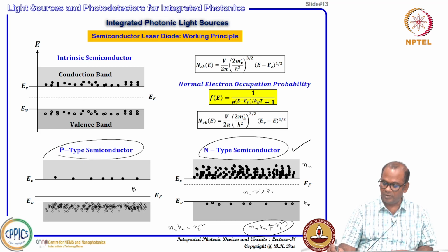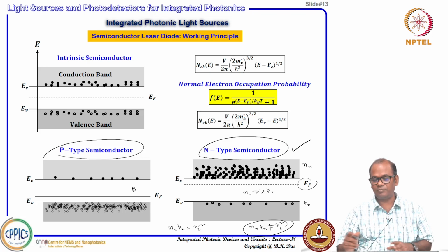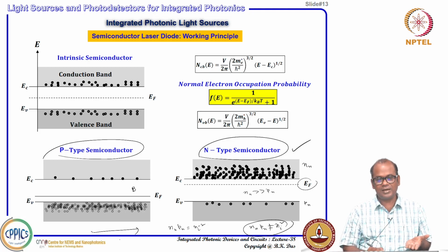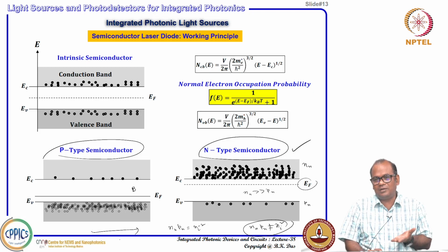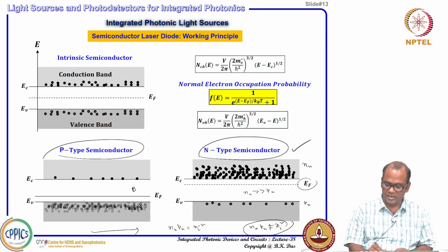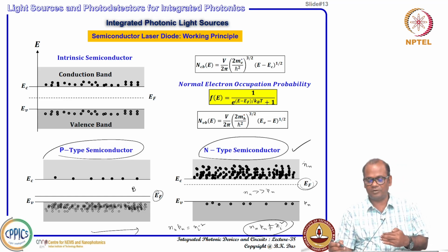where a pentavalent material is doped, so that a lot of electrons are there. You see, on one side the Fermi level is lower, on the other side the Fermi level is higher. But you know, in a semiconductor it is continuous as a function of x. You cannot say that the occupation probability for a particular energy state at the n side will be somewhere here, at a lower Ef region, and the occupation probability of half here will be higher. That cannot happen.